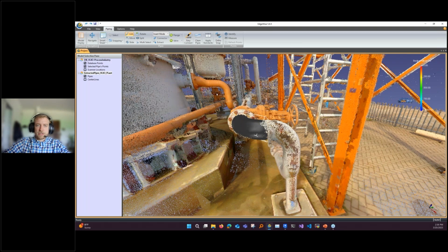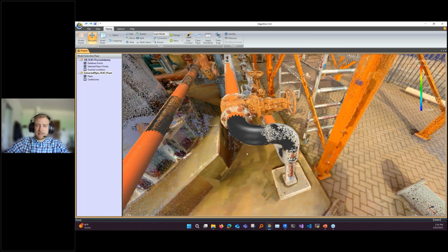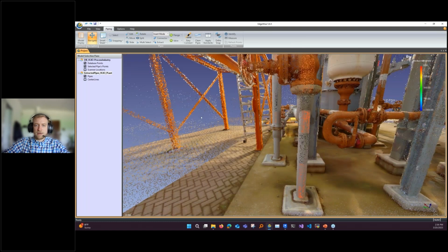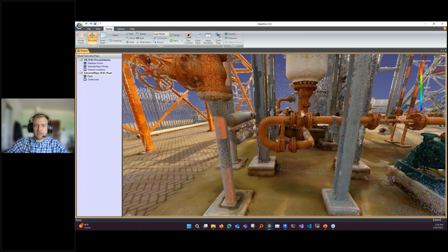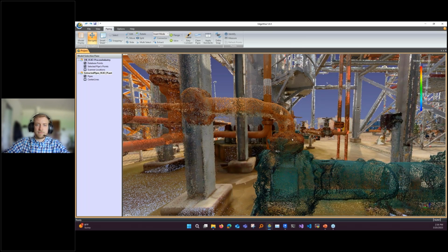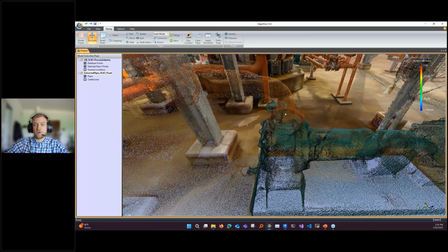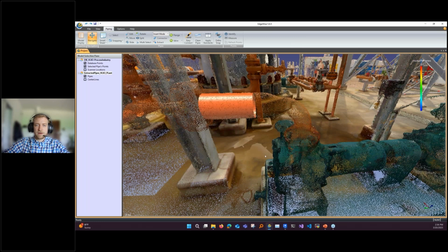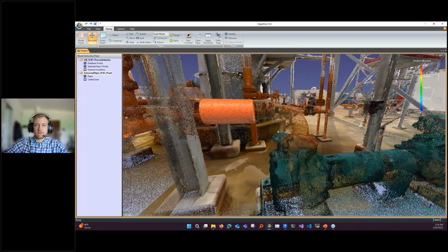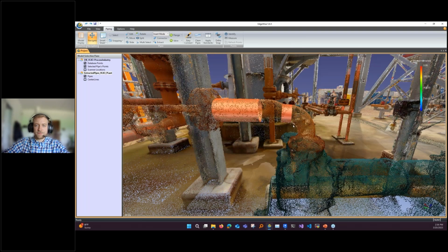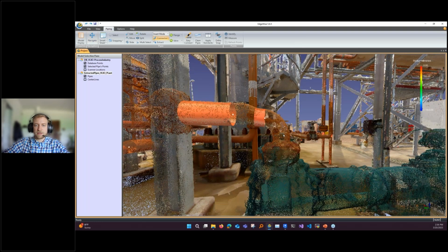But the question is, what if I can't get that little pipe segment? That's the thing that we were able to do in this specific example, but there's probably another one in here somewhere where that's tough, just because the bend radius is very tight. This is a good example right here. It goes basically an elbow, a pipe to a reducer to an elbow straight into a valve, right? In order to model this, I'm going to first extract a pipe segment there. I'm going to try and extract a pipe segment here. Again, I'm doing little slivers. I'm going to try and extract a little segment down here, and we'll see if we can. Even if we can't, it actually looks good. That would be the approach.